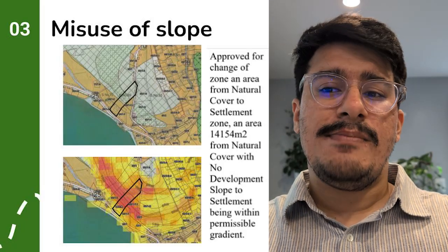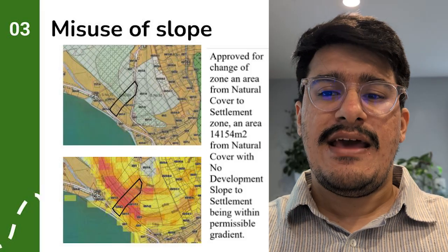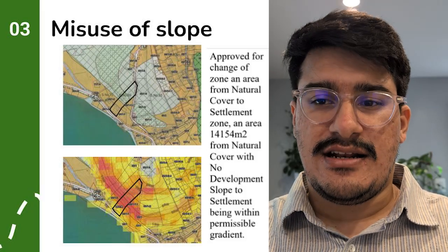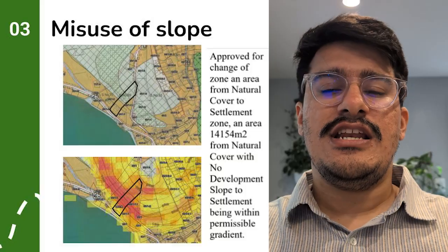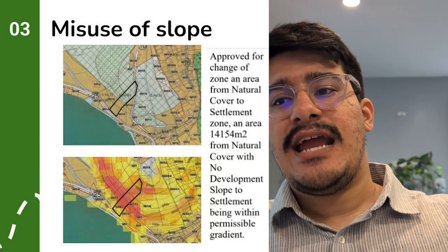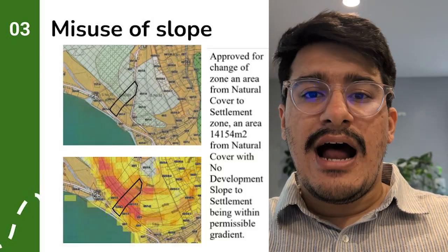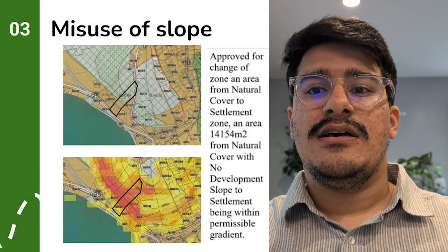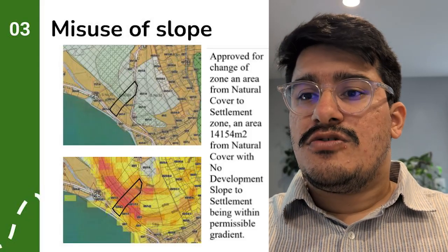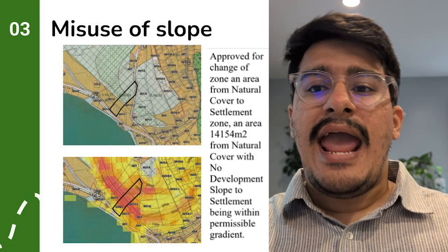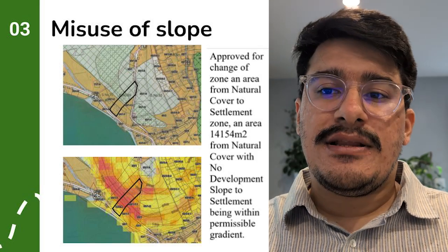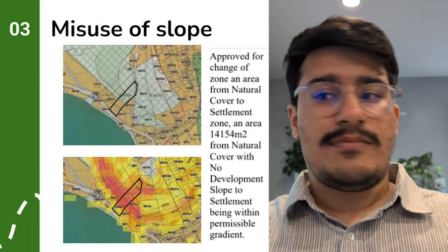Remember, some of you will be in the position of planners. Please make an effort to regulate strictly. Regulators usually don't mean the entire site, because plot boundaries are artificial and created by humans. Nature does not adhere to plot boundaries. Any portion of the land that's steeper than the threshold percentage should not be disturbed.